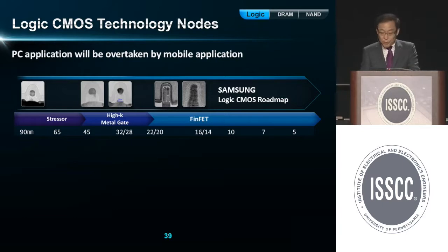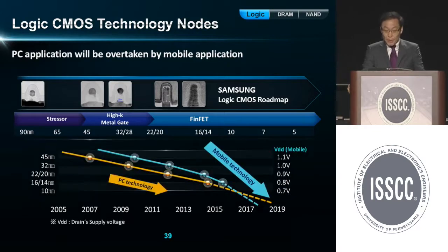The wrap-around gate structure of FinFET provides better electrical control of the channel. Thus, it helps in reducing leakage current and overcoming short channel effect. All these technologies have been implemented to boost PC performance, which years later were also adopted in mobile devices. However, because of high demand for mobile computing, technology adoption time gap is narrowing.